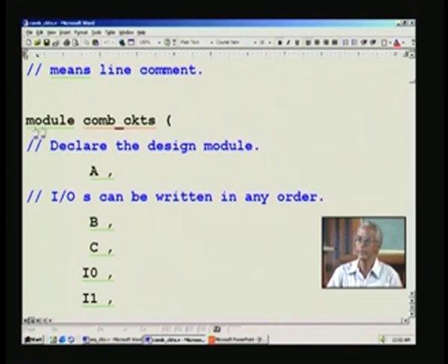And once again we see there is a module here, and the code might be a long thing. So, you normally tend to forget an endmodule towards the end. If you forget, the compiler will tell you, but initially for beginners it may be difficult. So, a good practice would be to put module and straight away endmodule and keep on keying in between, so that you will not forget.